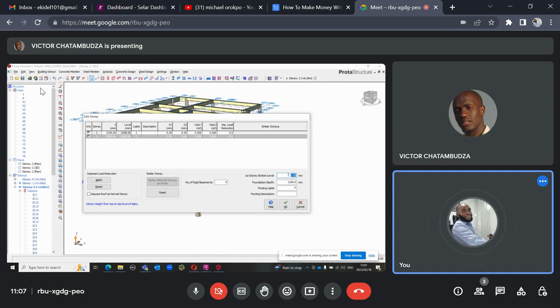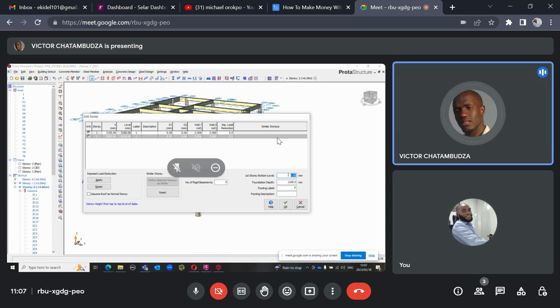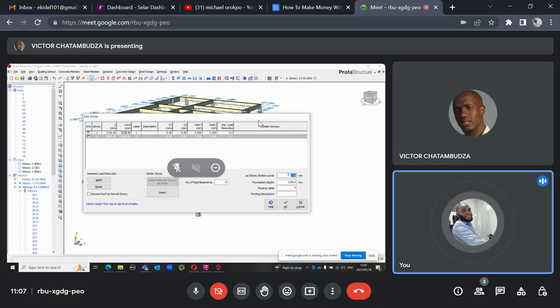Can you hear me? Yeah, I can hear you. Okay, so let's now put our DPC level there as 450. Since this building is just for domestic use, let's put there 450 as our DPC level.